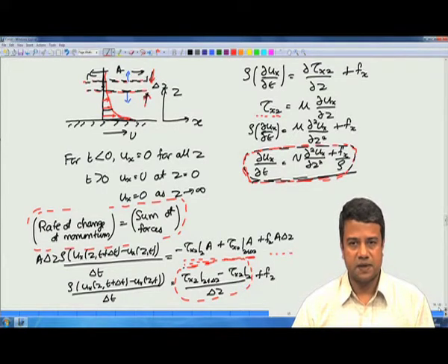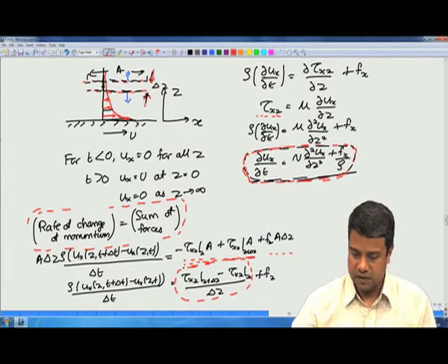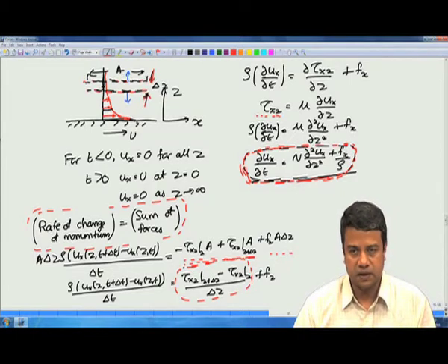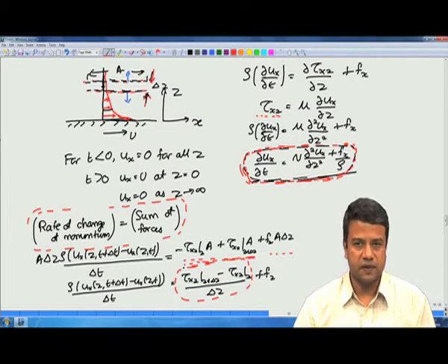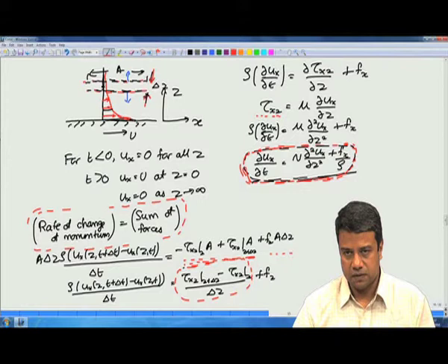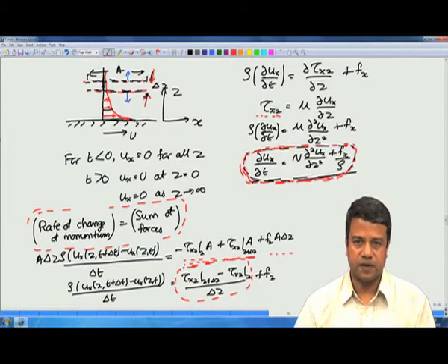In all of these cases we get exactly the same form of the equation, the diffusion equation, which contains one derivative in time and two derivatives in the spatial coordinate, and contains the diffusivity, whether it is for mass, momentum or energy, and it contains sources of mass or energy or the body forces in the case of momentum.